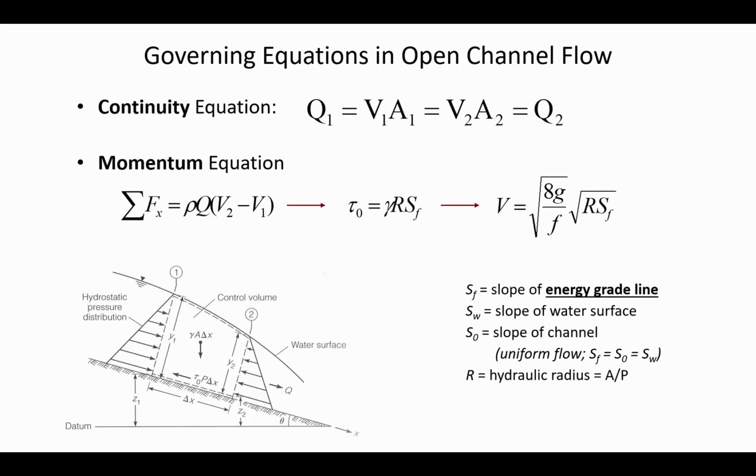And because in the force balance there's less force at 2 than there is at 1, this is moving to the right. So the governing equations that we're going to apply this semester: continuity will continue to be very important, where we could do a balance between the flow rate in and the flow rate out at 1 versus at 2. And so there can't be any accumulation here if we have steady flow.